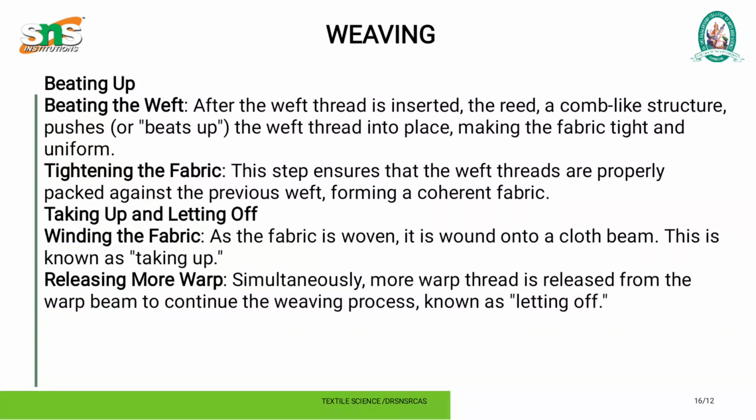Beating up. Beating the weft. After the weft thread is inserted, the reed, a comb-like structure, pushes the weft threads into place, making the fabric tight and uniform. Tightening the fabric. This step ensures that the weft threads are properly packed against the previous weft, forming a coherent fabric.